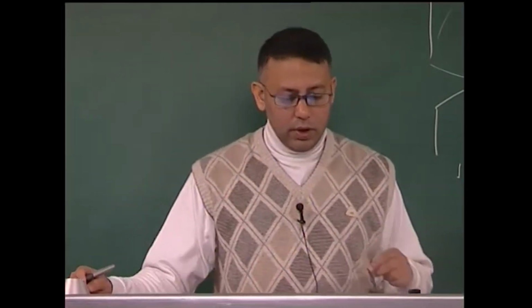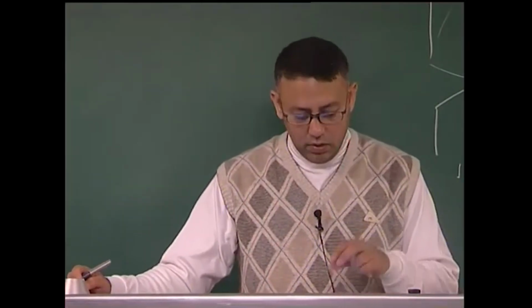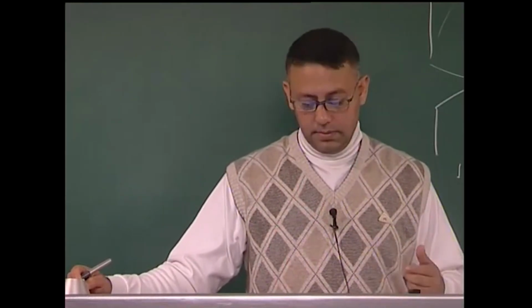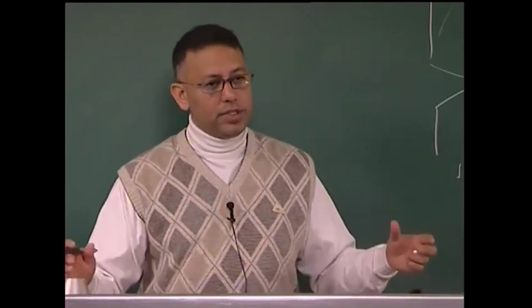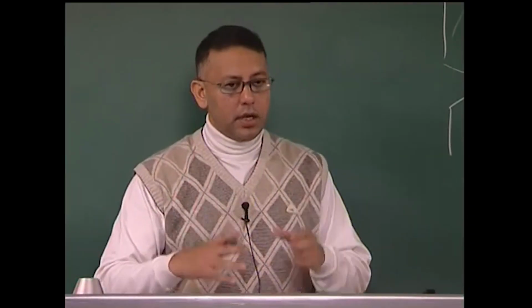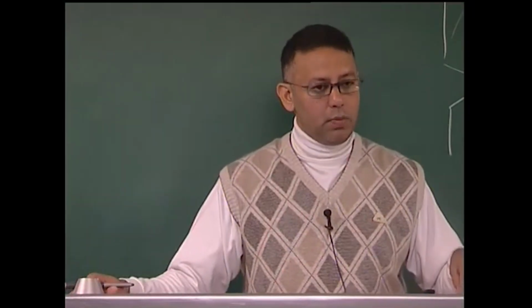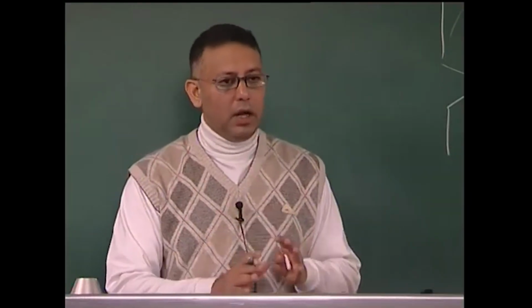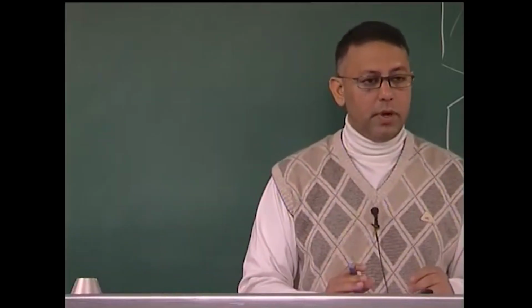To summarize this slide we have just now seen, we will notice that when we are at the length scale of the individual atom, there is a lot of disorder, there is thermal vibration. At the length scale of a few unit cells, we see that crystalline order has developed. And when I am talking about say a few tens of unit cells, the atomic vibration is much smaller compared to that length scale, and definitely at the grain length scale, I see that things are completely ordered with respect to this thermal vibration.